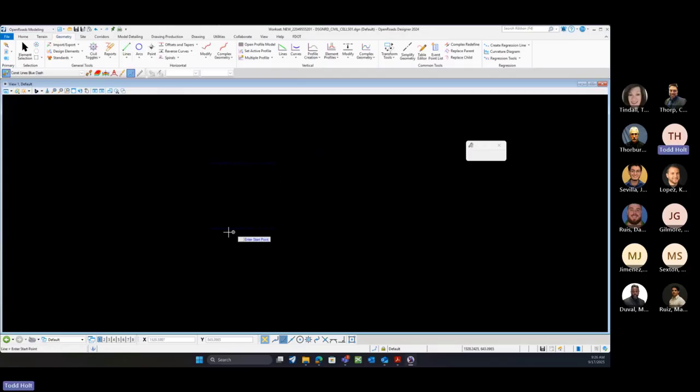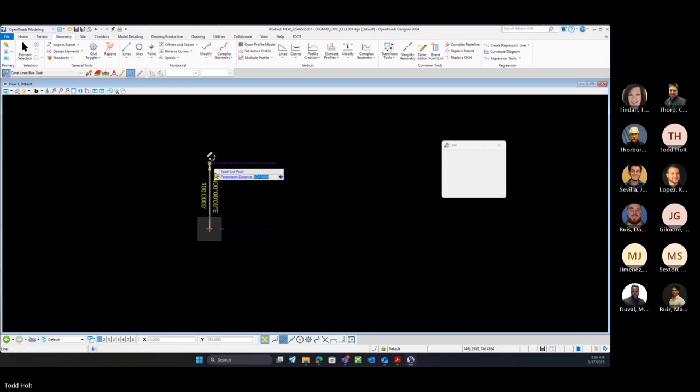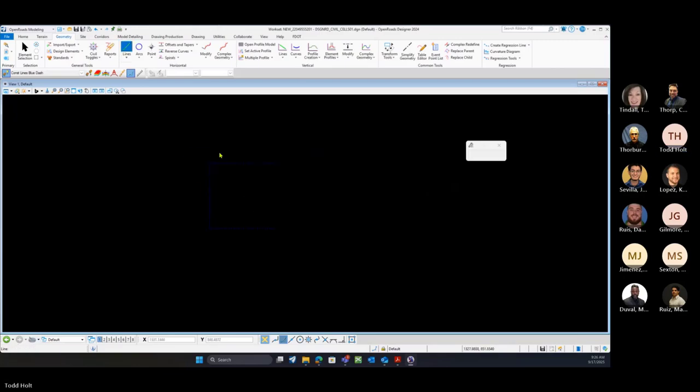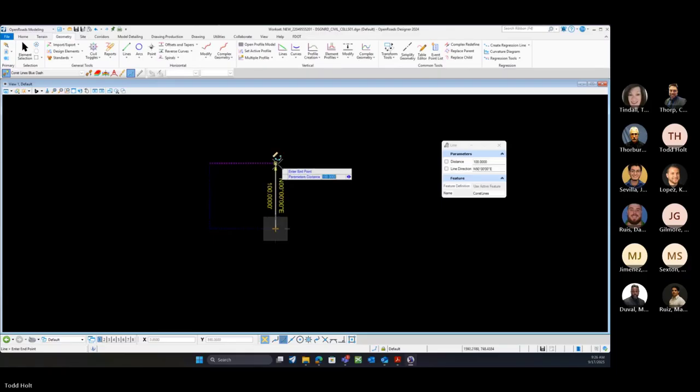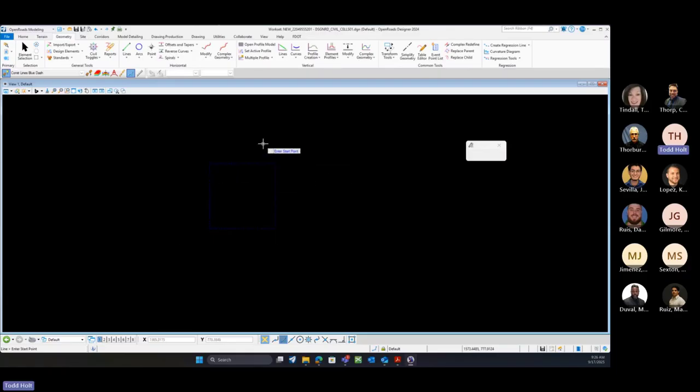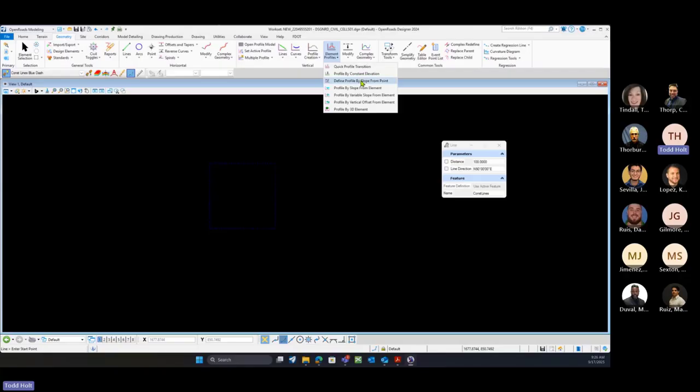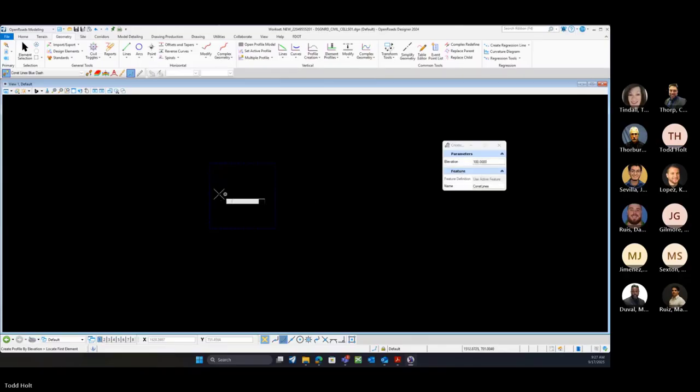And then from here, I'm just going to come in and build my line. So there, I'm just going to build a shape. And then from here, what I'm going to do is I want to give those constant elevations. So I'm going to come in here. Let's just say we're going to build this up at 100. So I'm going to use this geometry, these construction lines, to build a terrain model that I can use to target. So there I have my terrain model there.